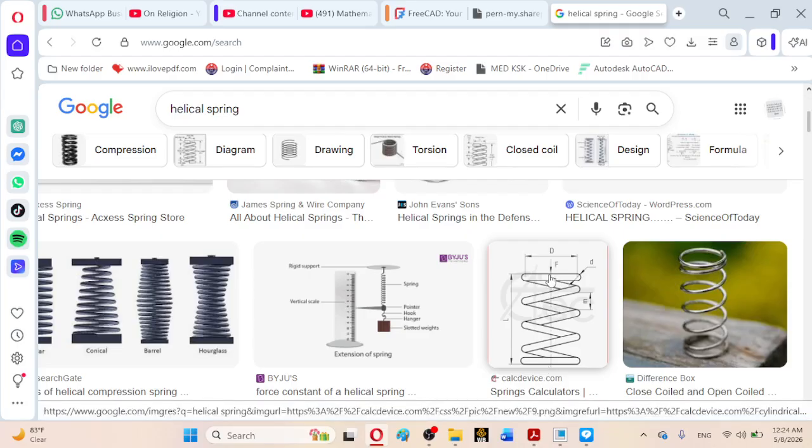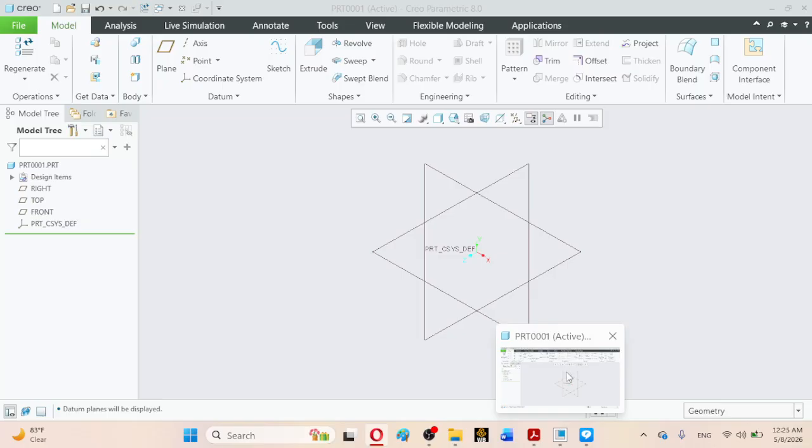As you can observe, the corresponding pitch points are the same at each and every point here. So in this way the sweep section will be swept along that trajectory or pitch points, and that trajectory will actually be revolved around this axis of revolution. So this is actually the concept. You will understand it further when I demonstrate this command.